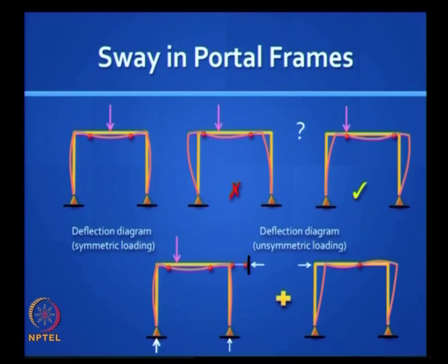And here you can clearly see why it is going to sway to the right, because the net load is going to act in that direction. You have to reverse the load acting on your artificial restraint. This is a beautiful, powerful left brain understanding of why the sway is always to the right, okay.